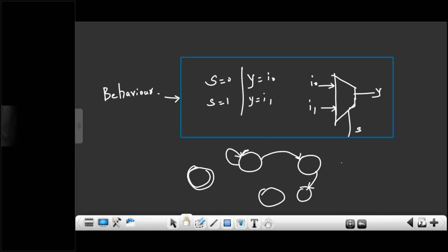After dispatching the amount, the last state is: collect your card. After that, it will go back to the reset state. In any state, if you don't enter your pin for more than a predefined time, again it will go back to the reset state. If you don't enter your amount in the predefined time, again it will go back. So describing the behavior of an ATM machine is easy through finite state machines.